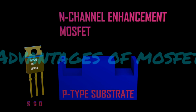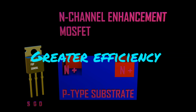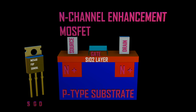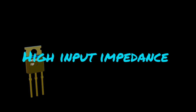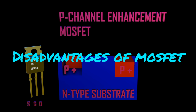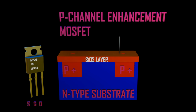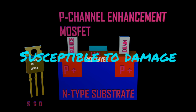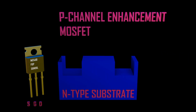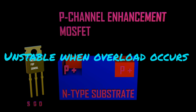Advantages of MOSFET. 1. It works at a greater efficiency, but with a lower voltage value. 2. As it has no gate current, it gives a high input impedance, which produces a high switching speed. Disadvantages of MOSFET. 1. It is susceptible to damage due to its thin oxide layer, which can get damaged because of electrostatic charges. 2. It gets unstable when voltage gets overloaded.